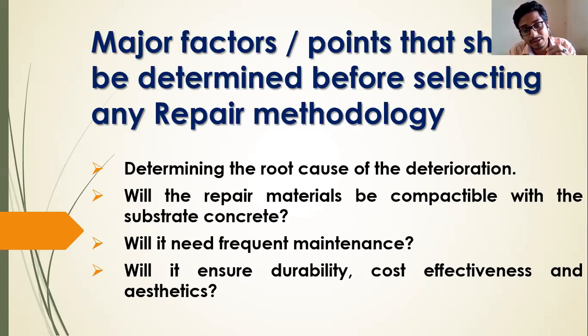Durability is the mechanism or process by which we can make a structure, concrete or whatever, persist for a long time against environmental loadings and structural loadings. Whenever you expose a structure to the open environment, it should last for a long time, according to the desired design period. If it serves this purpose, then we can say the structure is durable. Kindly go through the literal meaning of durable, and don't always come up with a test. RCPT is only one test for determining durability.